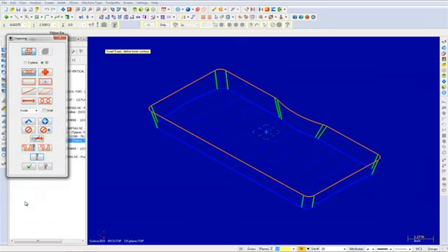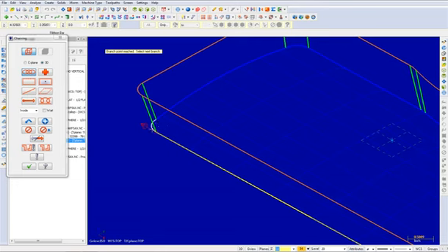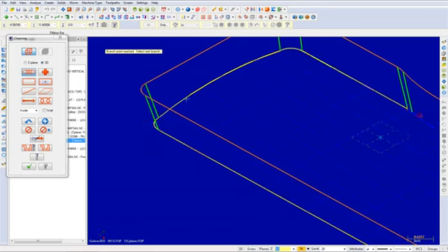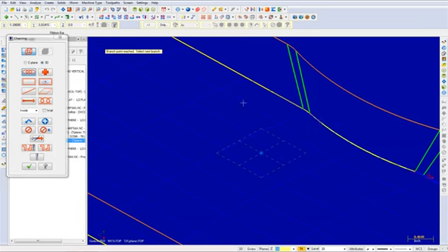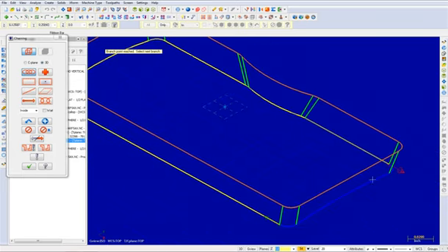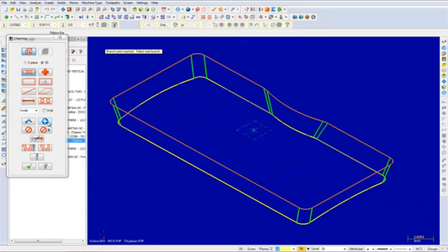Select the OK button, and then select the lower rail starting here. Continue around the part if needed. Then end the chain and chain the upper railing in the same manner. Once complete, choose the OK button.